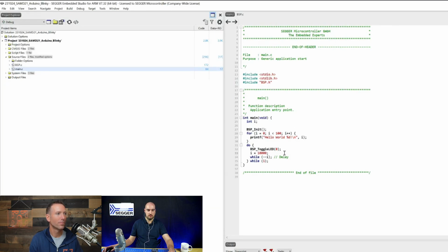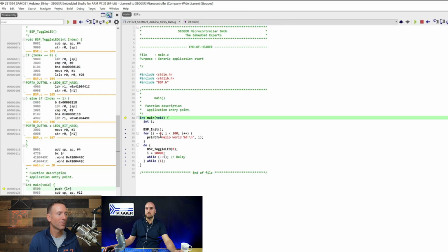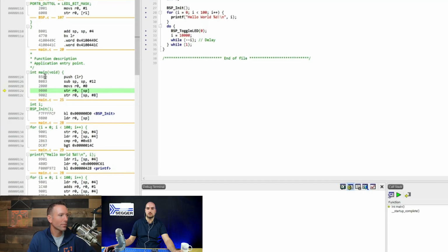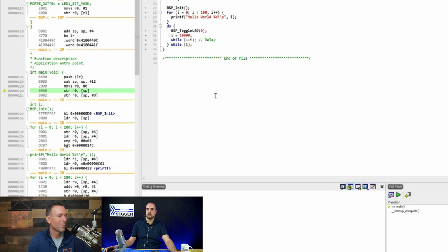And if I let it run, now we again can step into functions. I'm now in the, I clicked in the assembly window. So this is something that we didn't see in the Arduino IDE. This is the actual machine code that's executed. So you see here, these are the addresses, and this is the bytecode that's executed. Oh wow! Okay. And this is explaining what registers are. Like you have a store of this value R0 to the stack and stuff like that, or the stack pointer is put into R0 and stuff like that. So you can see what the machine is actually executing.